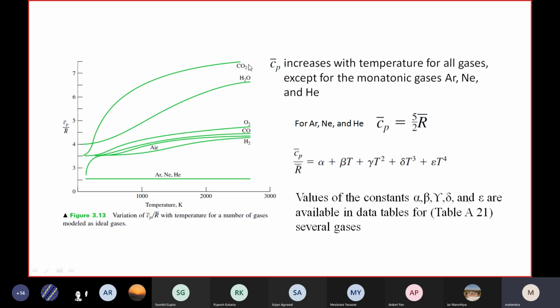If those gases are lost to the environment, it means efficiency losses are very high, because they are carrying so much heat, whatever the mass is going, at the high temperature, m Cp delta T. Obviously, it is at high temperature. By the virtue of temperature itself, losses are very high. The Cp capacity is also very high. So that's why losses are very high over there.